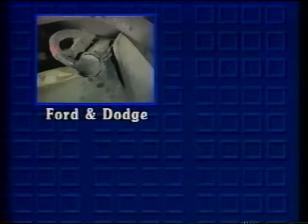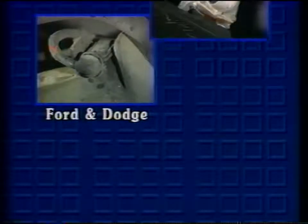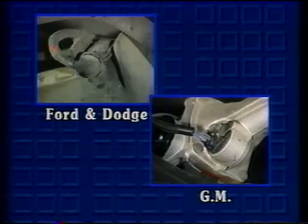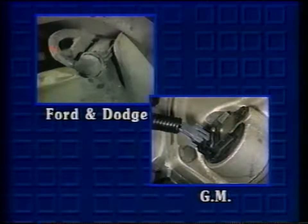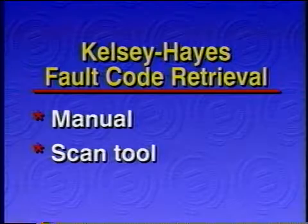The controller receives a speed signal from a single vehicle speed sensor. On Ford and Dodge applications, you'll find the speed sensor in the differential. The sensor ring is on the ring gear. On GM applications, the speed sensor is located in the transmission tail shaft, and the sensor ring is on the transmission output shaft.